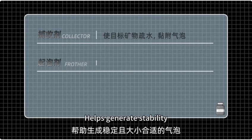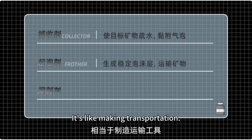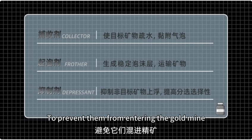What about the foaming agent? It helps generate stable bubbles of the right size. It's like making transportation. The inhibitor is to prevent waste rock minerals from sticking to air bubbles, so they don't enter the concentrate with the gold.